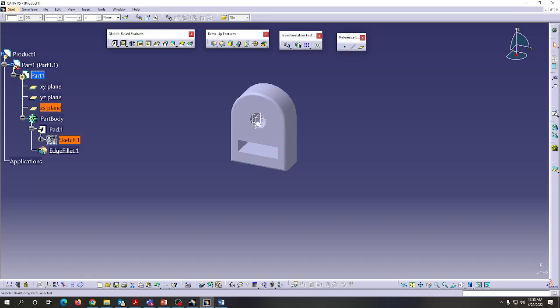It means the sketch can be changed at any time. Even if you finished your full assembly, and you want to change the diameter, change the length, or modify the sketch, everything can be done. That is the meaning of a parametric application.